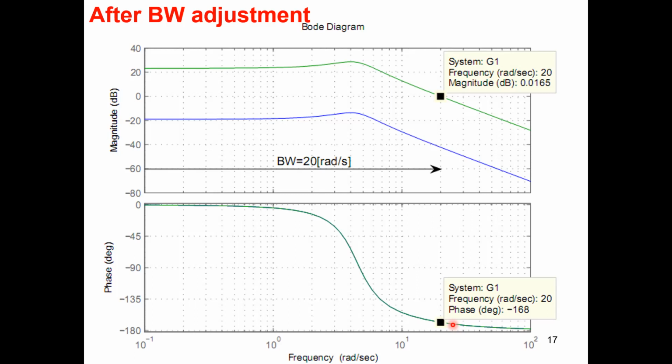And if that makes the perfect combination for disaster, that's something you need to avoid. That is why you need to maintain a wider margin, 40, 45 degrees. In that case, even if the margin changes a little bit, 5, 10 degrees, you still have sufficient margin to be stable.